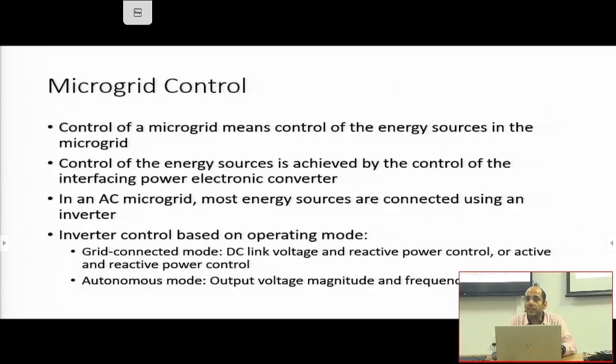And the PWM switching is done on the basis of one high frequency carrier and a fundamental frequency reference signal, right? Now, how do you generate that fundamental frequency reference signal that will define how your PWM signals will look like? Those PWM signals will decide when your power electronic switch in the converter will be turned on and turned off. When the device turns on and off, based on the duty or the period when it turns on or off, accordingly your output voltage of that converter would change.